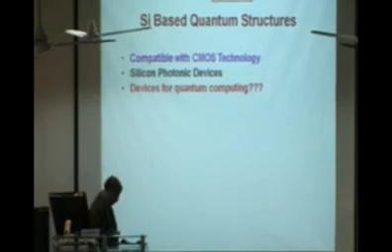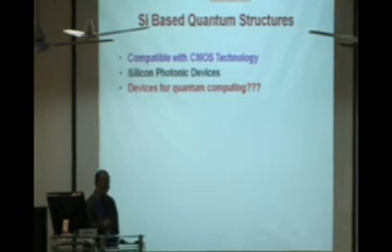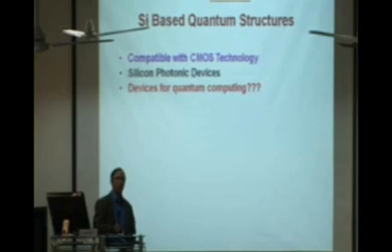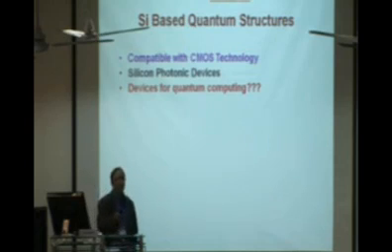And the other motivation is that before quantum computing, there is another term called optical computing or photonic computing. Can you do information processing inside the chip using photons? Even that speed will be much, much higher compared to the conventional computer that you use. Unfortunately that has not yet been achieved, though it has been talked about for the last 30 years or so, because one of the problems is that you don't have a silicon laser in production or in the market, or it's not possible to make, because silicon is basically an indirect bandgap material.